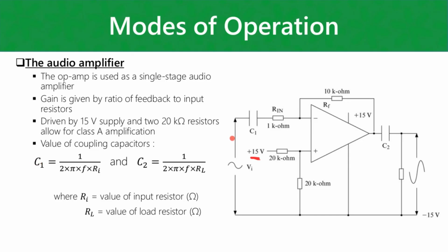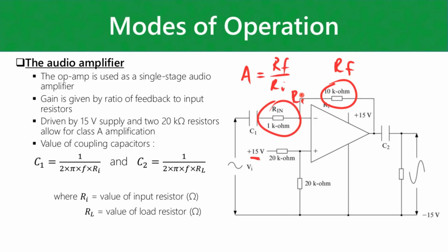All right, so for this circuit, what is important is working with the input and output and gain, for instance. The gain for this circuit is just going to be your feedback resistance, RF over Rin. So this resistor here, that's RF, it is labeled there, and then that's your input resistance right there. So your gain is the same, maybe just put a negative sign there. So it's the same as for an inverting amplifier.